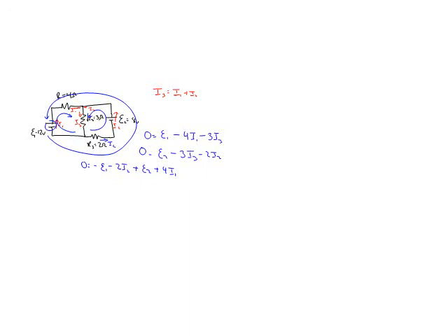So we have 4 equations even though we only have 3 unknowns. The other thing that I'm noticing is that I put in the resistances, but I didn't put in the E's. It's kind of silly. So I'm going to just go and replace those E's with actual voltages. E1 is 12. E2 was 8. There you go. That will let you skip this a little bit.